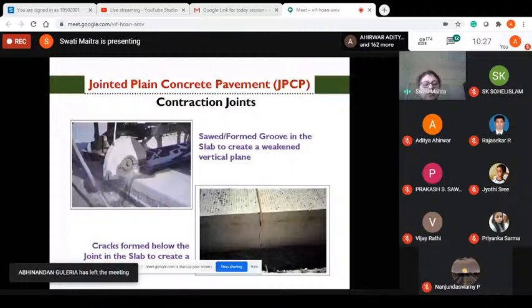As you can see from the previous slides, the closer the deflection of the unloaded slab is to the loaded slab deflection, the better the load transfer. You can also find it from this expression: if delta UL, the deflection of the unloaded slab, is very close to delta L, then we have almost 100% efficiency. 100% efficiency is a theoretical thing.